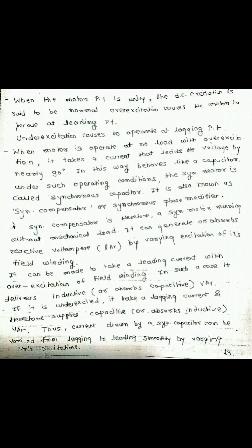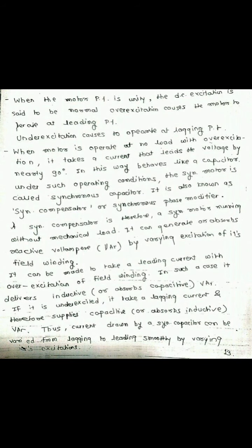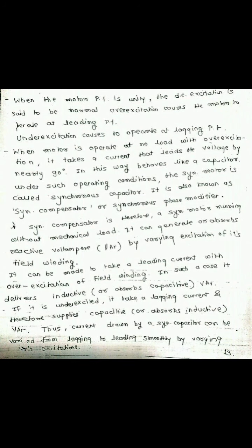In the underexcitation state, it takes a lagging current, and therefore it absorbs inductive reactive power. Thus, the current drawn by a synchronous capacitor can be varied from lagging to leading depending upon the change in excitation.